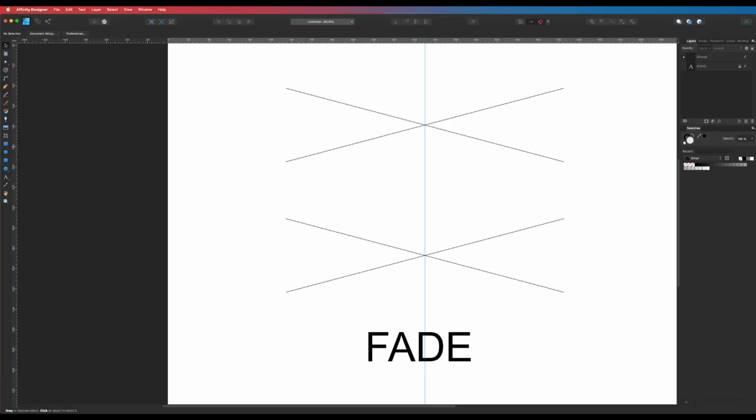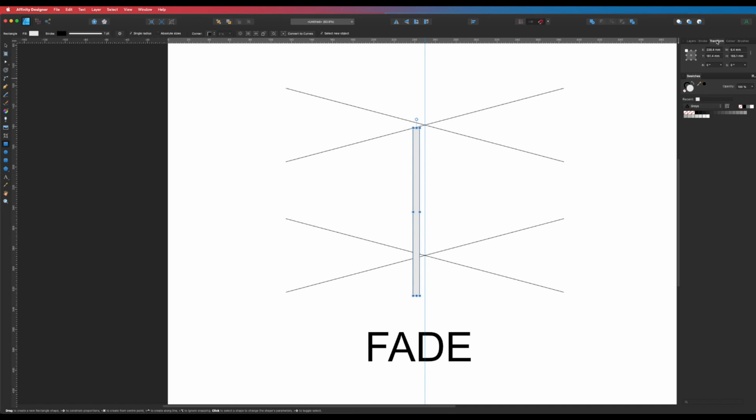It shows your lines. So let's draw a rectangle. I'm going to go over here, get my rectangle tool, or push M. And what I'm going to do with this, I'm going to go somewhere around about here. I'm going to click and I'm going to drag somewhere around about there. That's cool. I'm going to go to transform, and I am first of all going to take this stroke off.